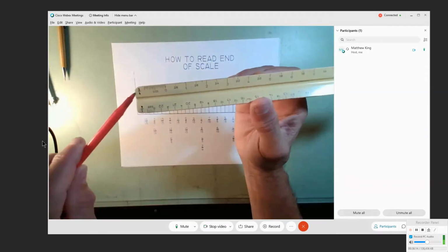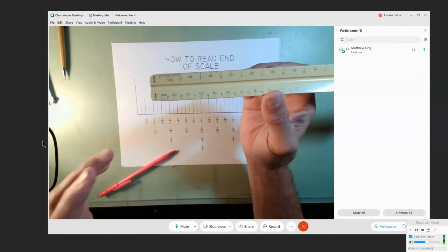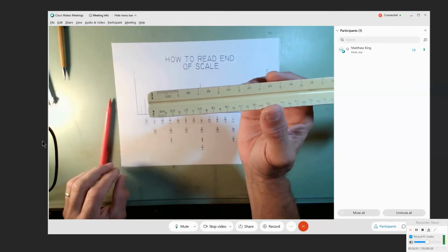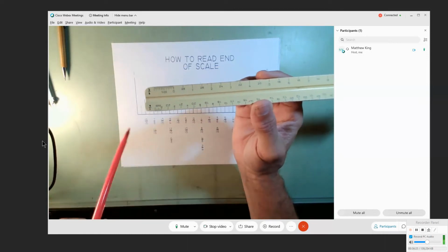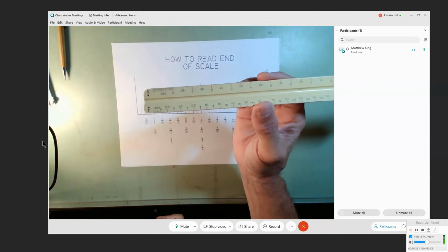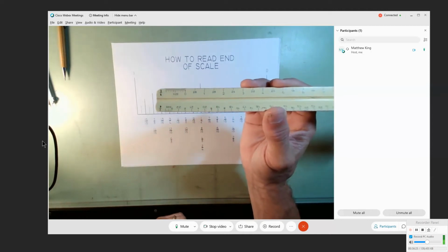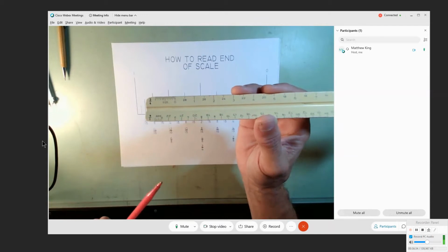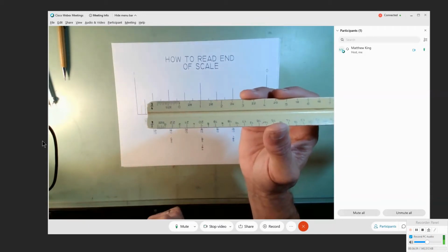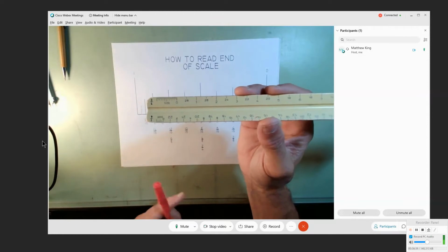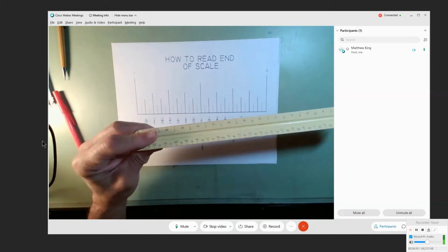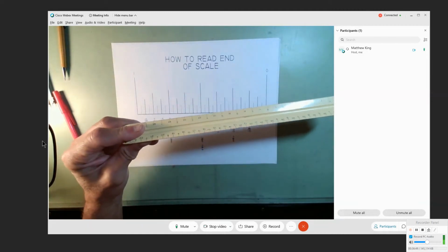Only it seems that the 3/4 size works best for us. We're only shrinking the drawing down a little bit, 75% actual size. But we don't have to change our method. We still measure and draw using this scale. It's just going to come out a little bit smaller. I don't have to take my numbers and multiply them by 0.75 or do any math. I just take the measurements and I lay them out to what the scale shows me, and they automatically come out 75% actual size. So I have to show you how to do that now. And if you want to get a piece of scrap paper, that's what we're going to do next.